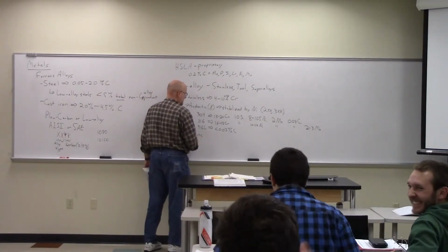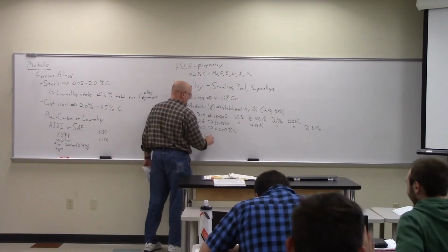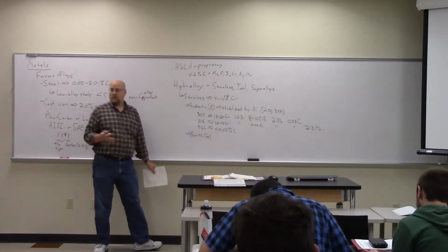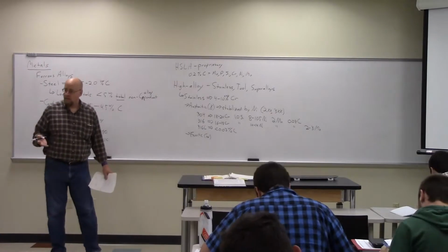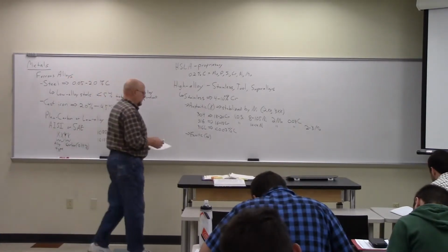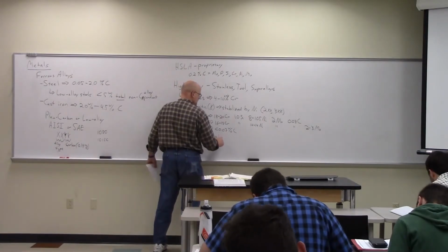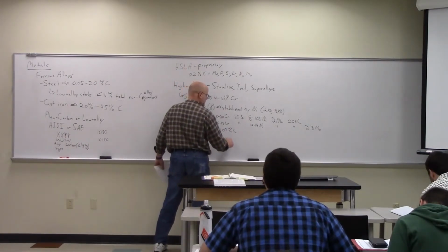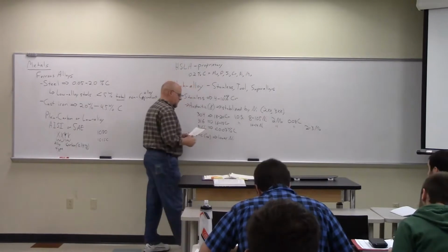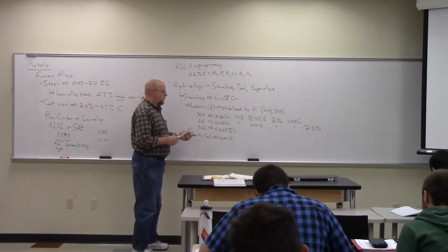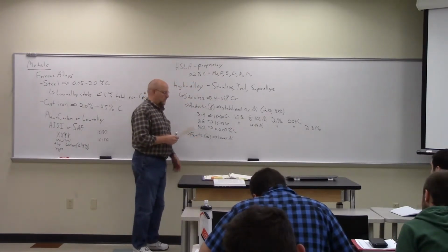It's probably also ferritic stainless steel, so it's alpha, right, which is normally stable at room temperature anyway. Alpha, because it has lower nickel content. So it makes the alpha, or the BCC form, stable at room temperature.